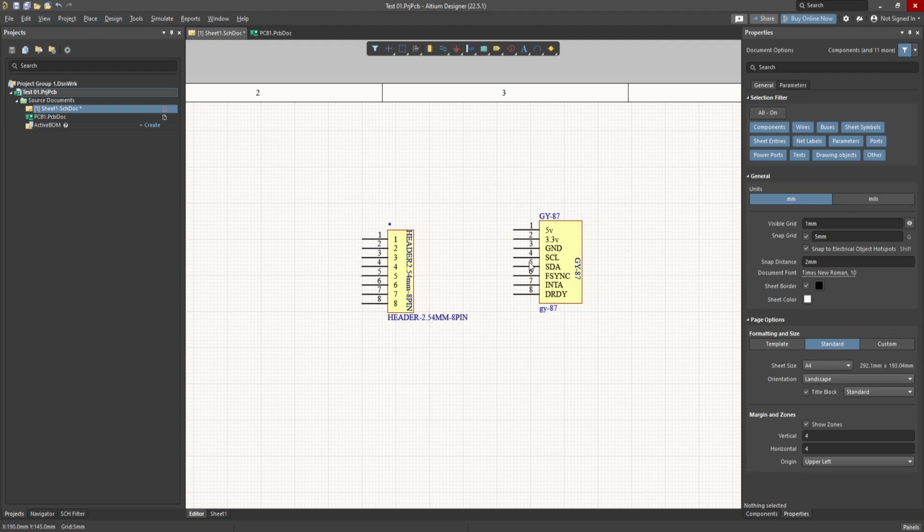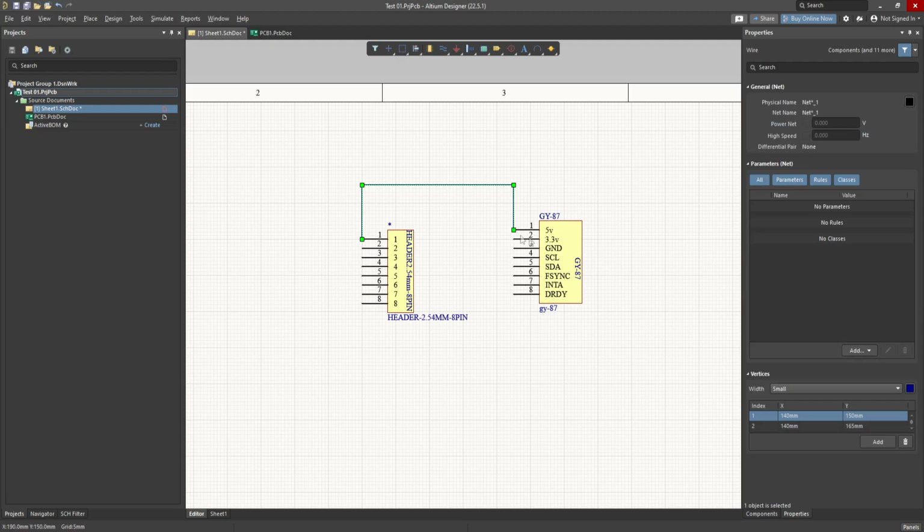So I just usually keep saving my project documents by clicking on this double floppy drive save icon in here. Okay, so the normal way to connect these two components is to press P for the place menu, or go here and wire. Click on this one, click, click, and click. So these two wires are connected one with one.